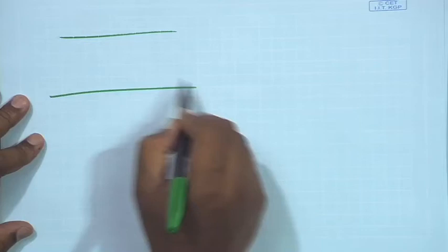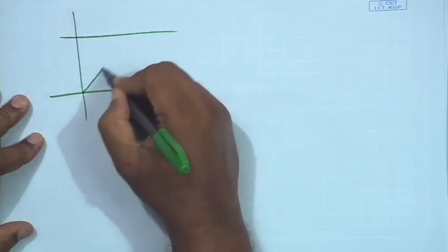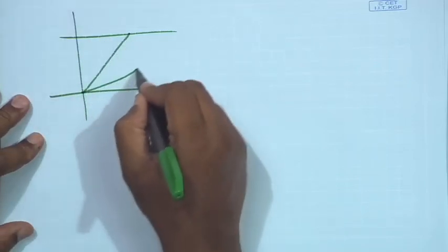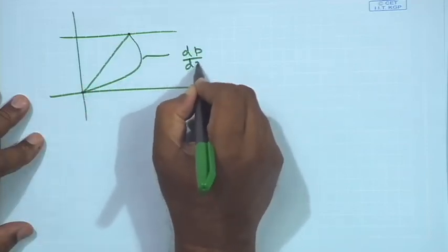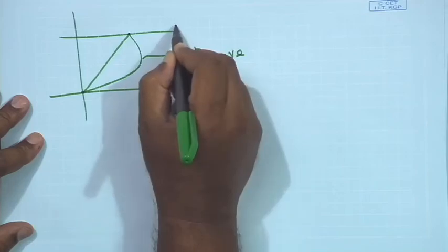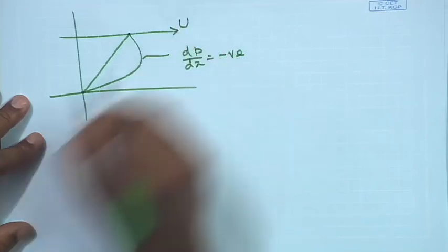So, initially it was a straight line Couette flow, and then when you start applying a favorable pressure gradient, the flow starts to deviate from its straight nature. Okay. When the applied pressure gradient is large, then you simply have the pressure gradient, the way I have drawn it previously, Couette flow, when you have dp dx to be negative. This is u, moving with u.